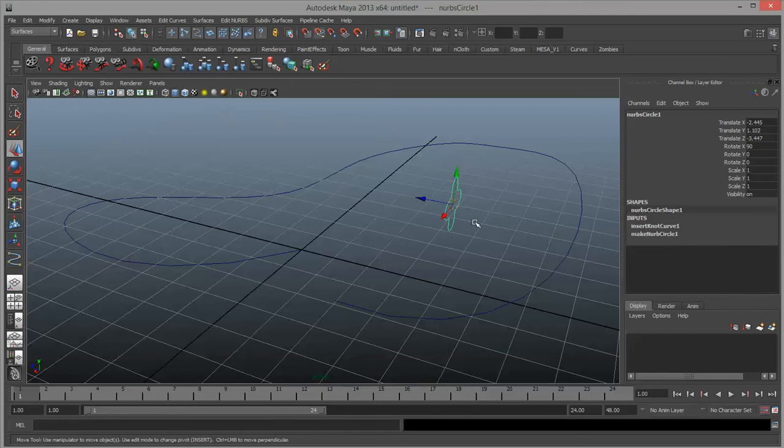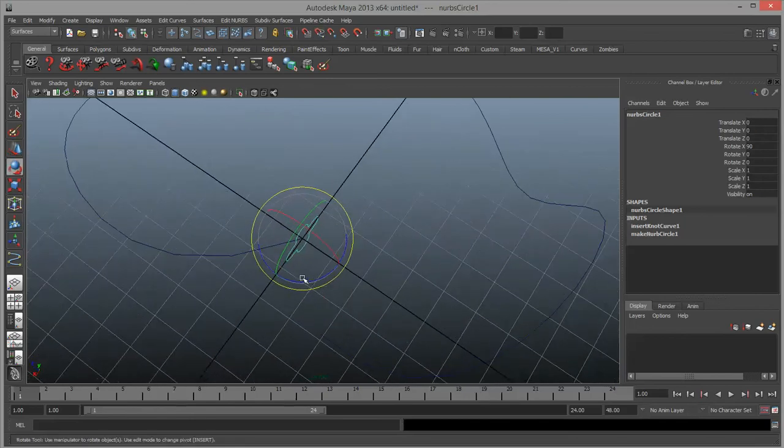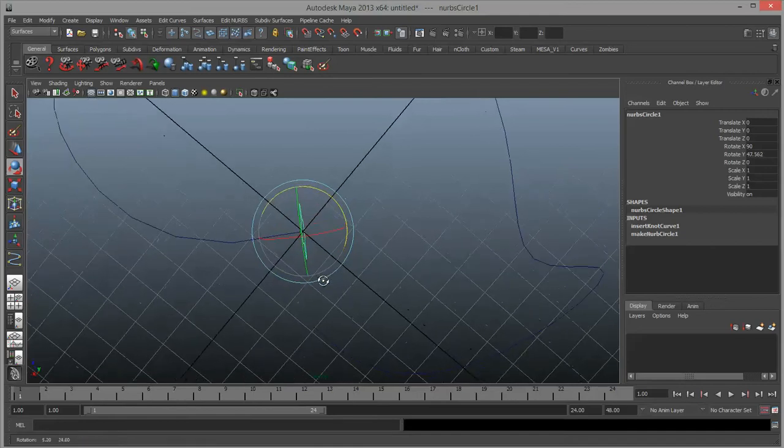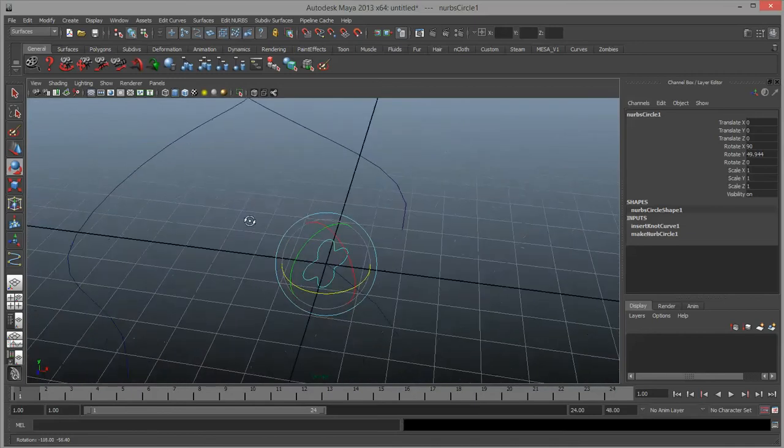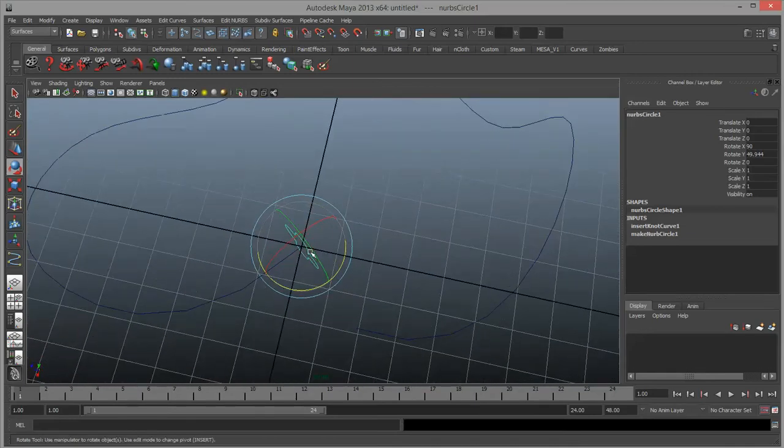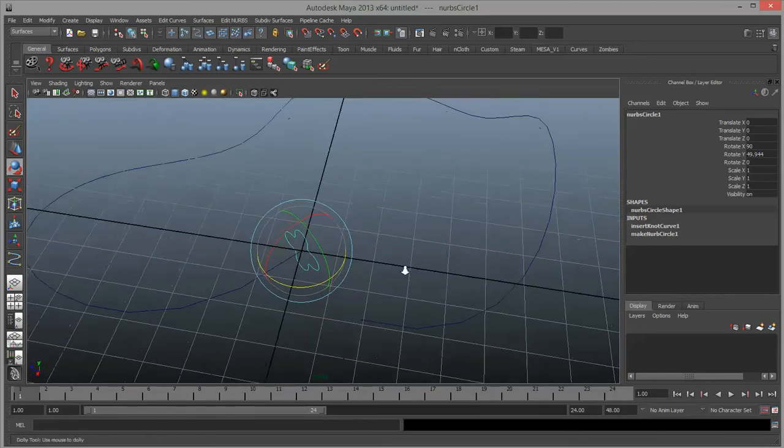If you hold down the letter C, and you can see this highlight at the top here, hold down the letter C and drag this from the center. Just make it overlap the line visually, let go of the mouse button, not the letter C, and then re-click and drag and it will snap to the curve. Okay, we can start it on this side of the curve or we can start it on that side of the curve. Just make sure it snaps to one of them. It is also sometimes helpful to rotate this to face in the direction that the line is going, although the settings in the extrude along curve function are probably going to take care of that for us. I like to do this anyway just to make sure that everything's taken care of.